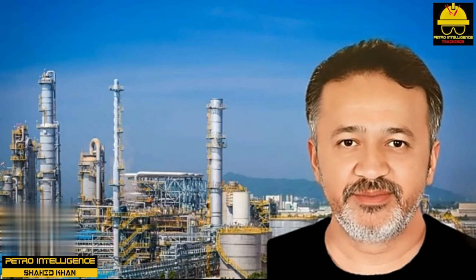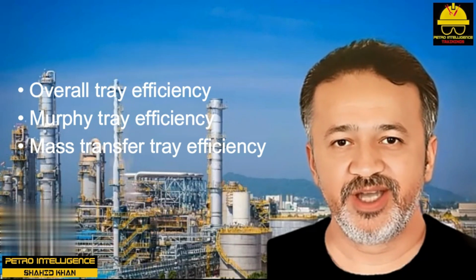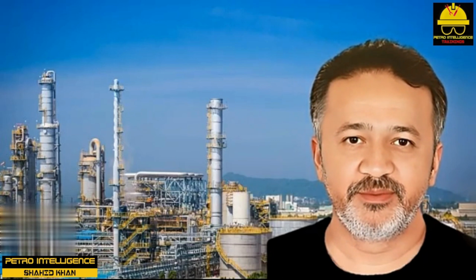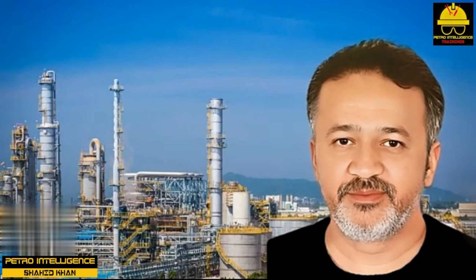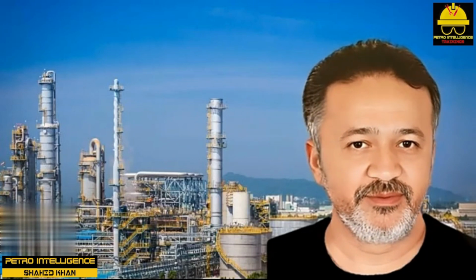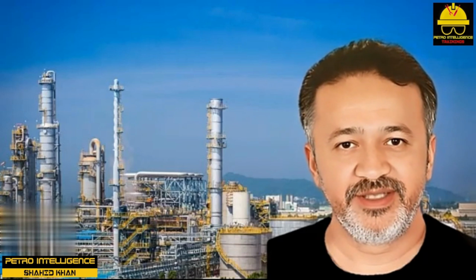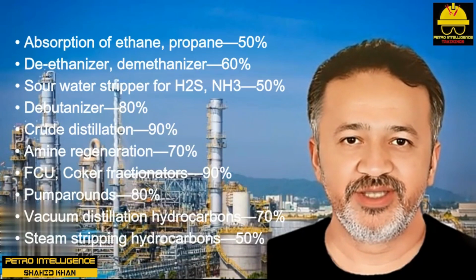Calculating tray efficiency. The viewer with a chemical engineering background will observe that I've neglected the calculation of tray efficiency. There are three methods available to calculate tray efficiency: overall tray efficiency, Murphy tray efficiency, and mass transfer tray efficiency. I've never had occasion to calculate tray efficiency for any distillation tower. I'm guided by observations on similar existing services. Certainly, tray hydraulics as described above, that is, levelness, weeping, entrainment, is the dominating factor in determining tray efficiency.